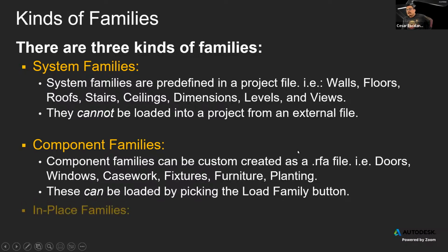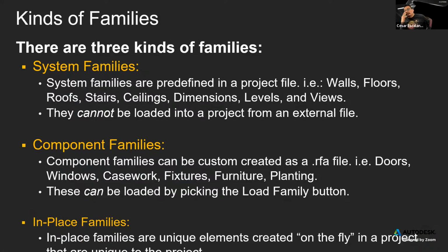And then there's another type of family that is called in-place families. These are families that are unique, that are created on the fly. They report a unique condition in the project. They are not intended to be used as a repetitive component inside a project. It's like building a family on the fly. It gives you access to the family editor commands or functionalities within the project environment.